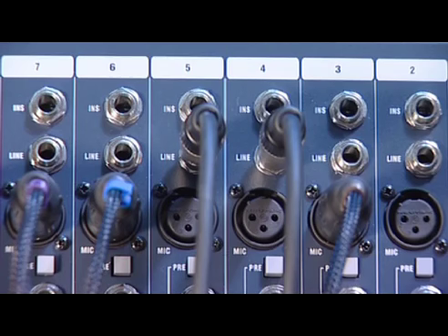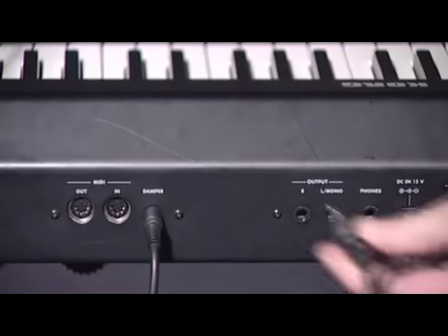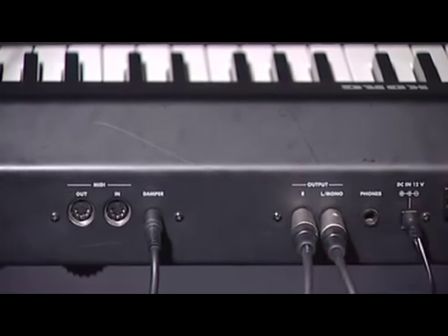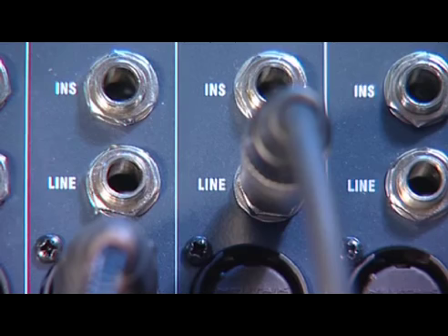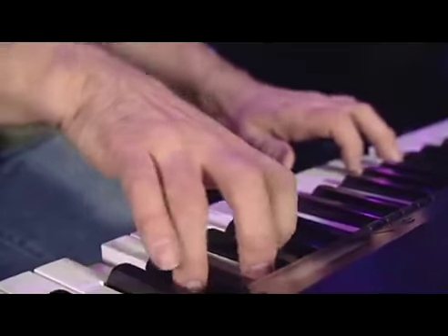It's not a good idea to use line inputs with microphones because the signal levels are much lower than line inputs are designed for. Usually, keyboards and MIDI units have stereo outputs. It's normally okay just to use one leg of a stereo pair and plug it into a single mono channel on the mixer. It's often only pseudo-stereo anyway, but sometimes a keyboard patch only sounds right when it is in stereo.